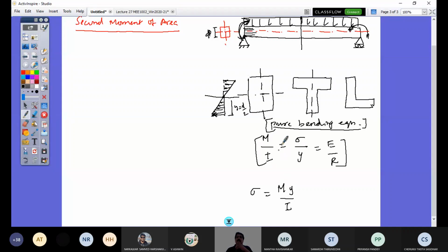And to get this bending moment at any section, if it is not pure bending but non-uniform bending, that means you will have a couple acting like this shown, and the UDL and some concentrated load at different span lengths. Then it is something called non-uniform bending of the beams. So still you can draw a bending moment diagram for that, and along the span, at every section, you'll know the value of bending moment.